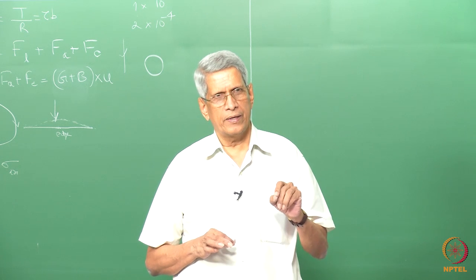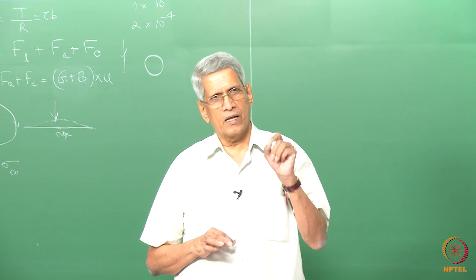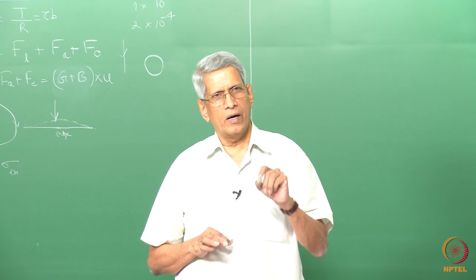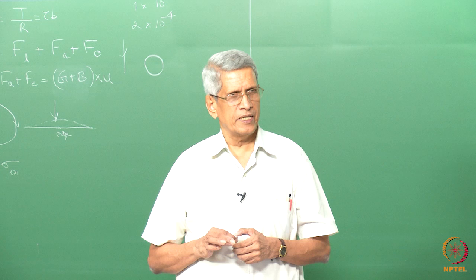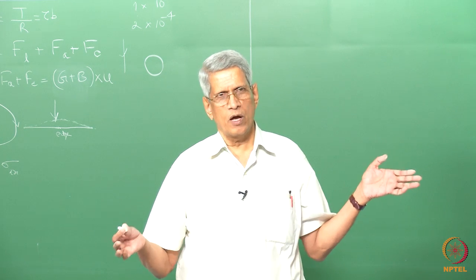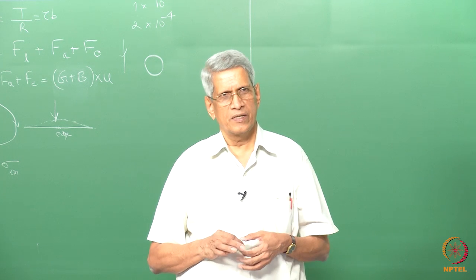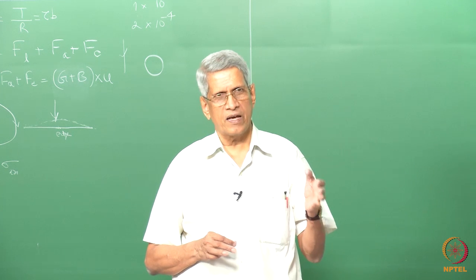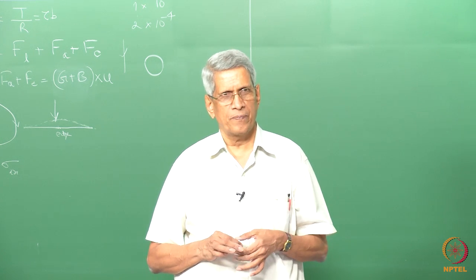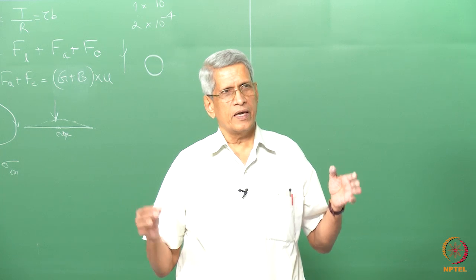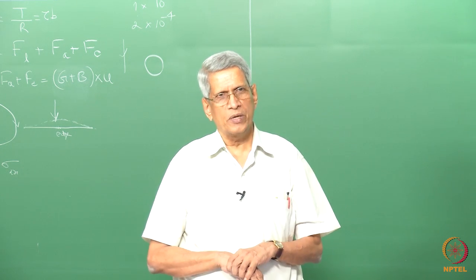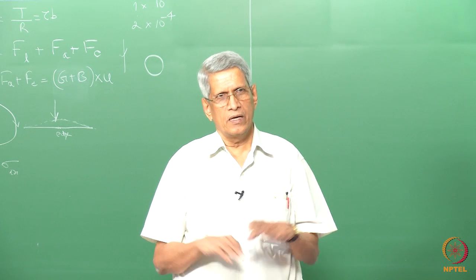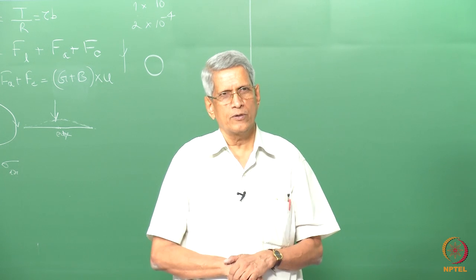That doesn't happen. Instead, a lot of dislocation loops are generated within the material. Okay. These loops also will generate some stresses in the material. These stresses are what we call the quenching stresses. The effect of these sort of stresses we can see where we don't allow the material for expansion to take place or a contraction to take place.